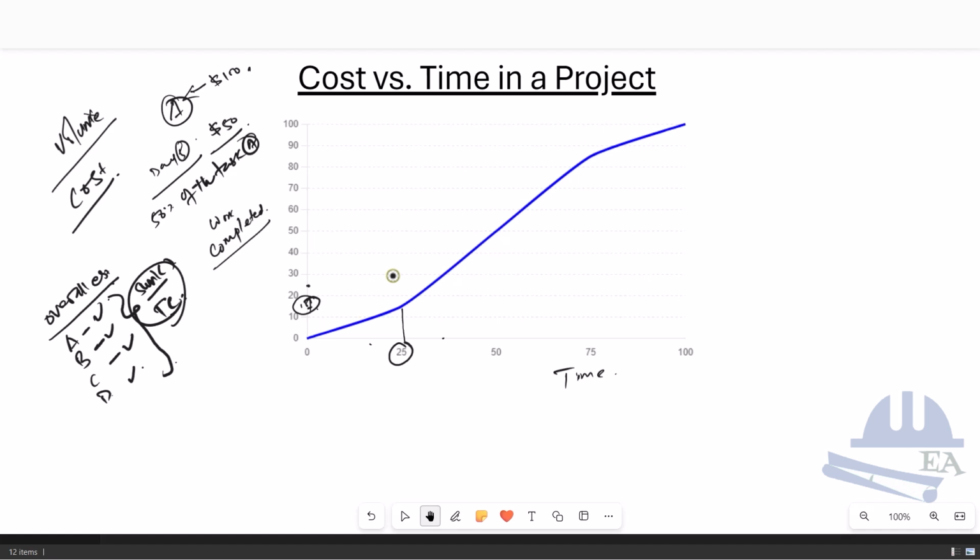The contractor going to the site is new, and he has to manage a lot of things. For example, he has to mobilize the manpower and resources, and he has to set up the camps, and also, you know, he has to start the site clearance, and he has to start the excavation and the foundation works. Normally in this 25% of the time, these many things happen, and they take quite some time: mobilization, excavation, and the foundation works. So normally for a building, we see that it normally takes 2 to 3 months for a moderate kind of building, without any deep foundation, to finish the substructure works.